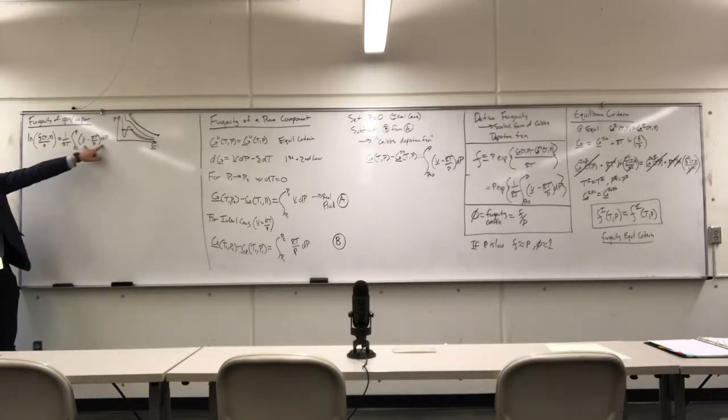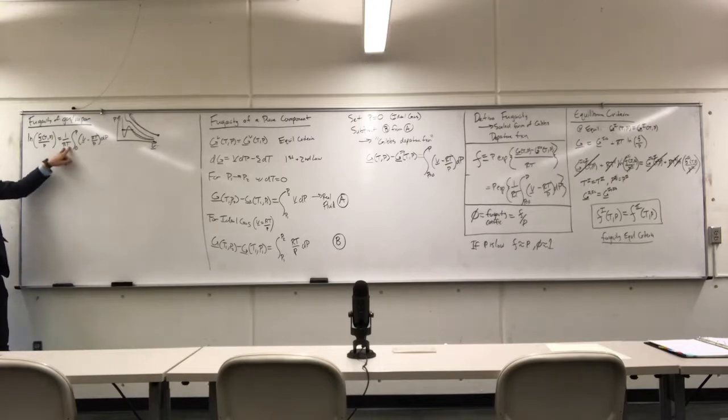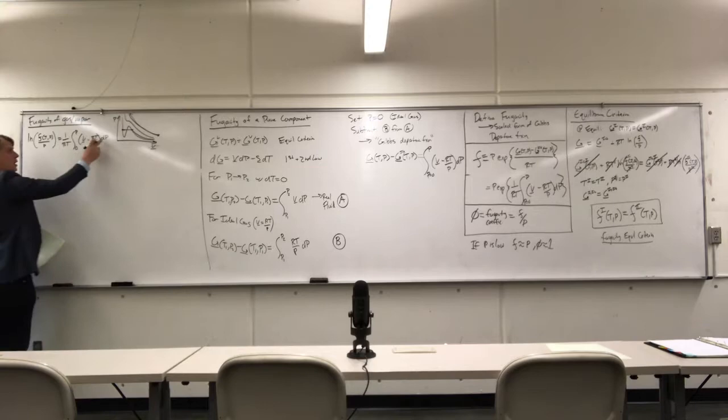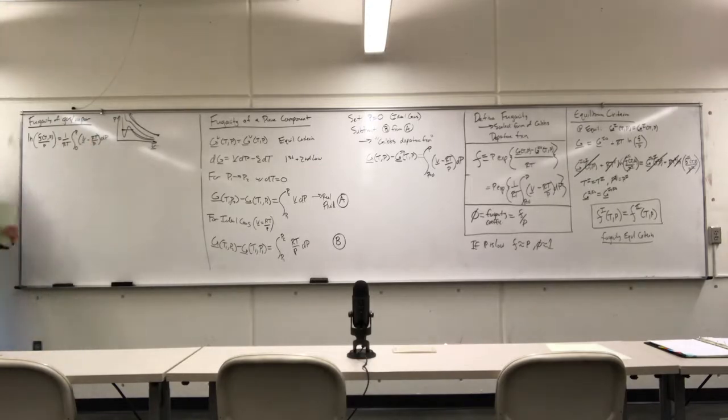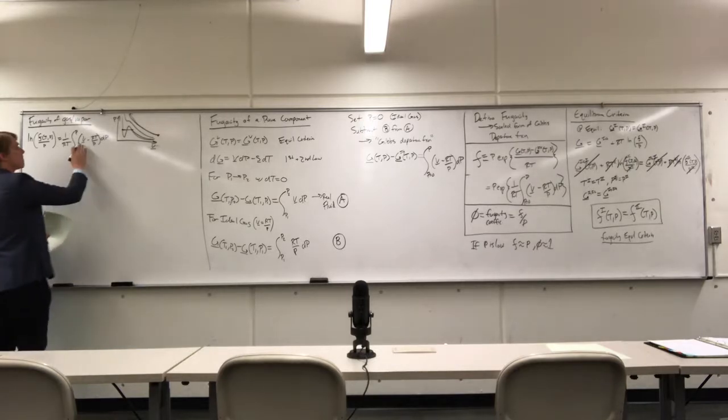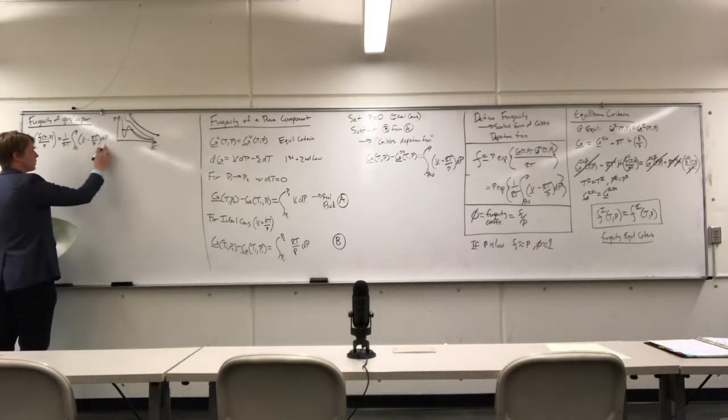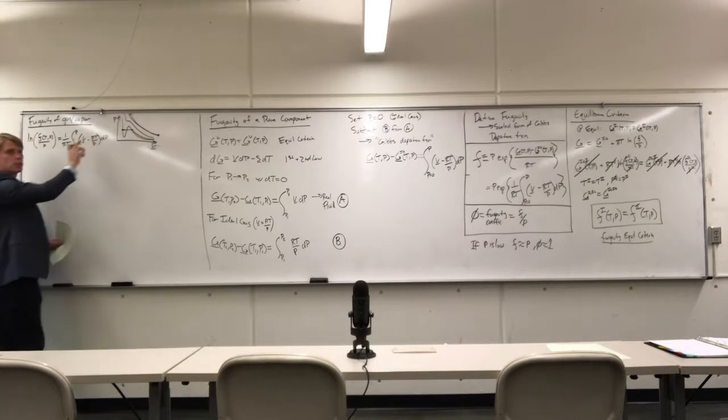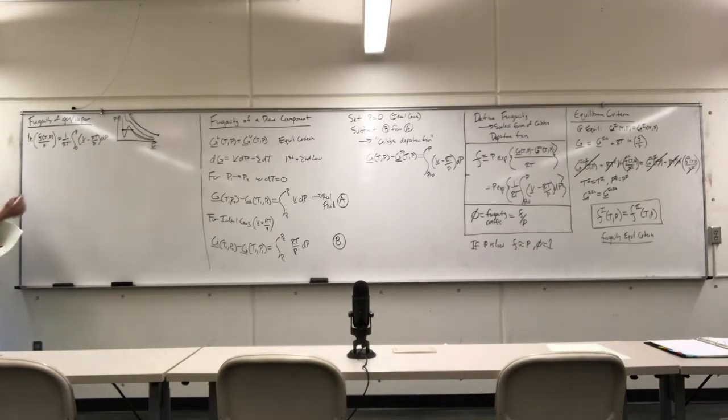Integrating V dP has units of energy. RT has units of energy. So this is unitless. Everything inside a logarithm has to be unitless. Everything inside an exponential has to be unitless. So this all works out that this is a unitless expression and this is a unitless expression. But integrating with respect to dP is not very useful. Most of our equations of state are pressure explicit, not volume explicit. So we need to integrate with respect to volume for most all of our equations of state.